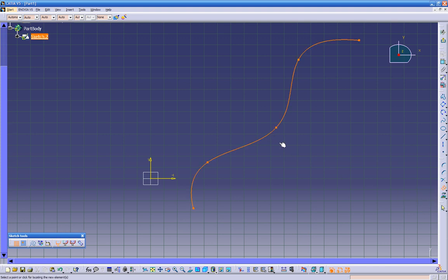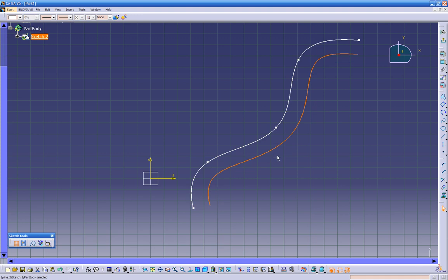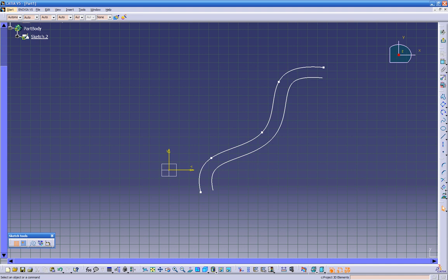Let's click on it, and we can offset it plus or minus. Before we snap it into place, let's hit the tab key a couple times till we get back here to the offset. And let's put our value to 5 inches. So that's our offset right there.